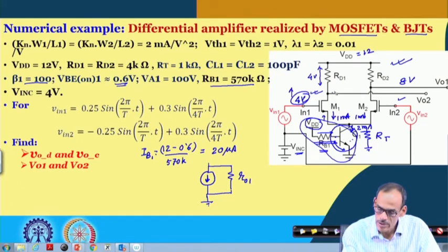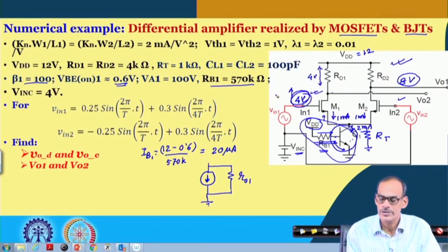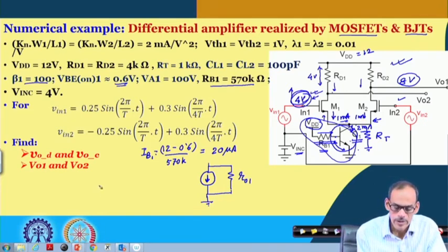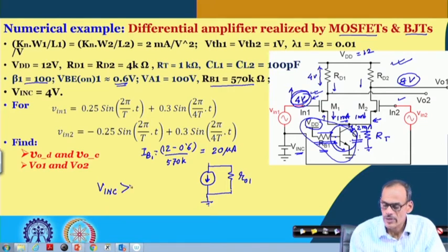So, I should say the DC operating point here is not really much dependent on this voltage, unless we are making this voltage very small and forcing the source node very low, pushing this transistor Q1 into saturation. So, as long as that is ensured, both this current and this current remain 1 milliampere.